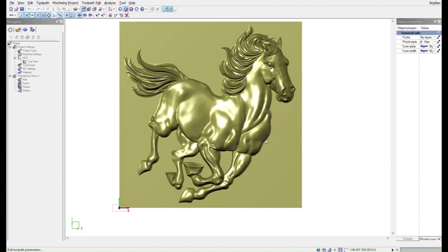So this basic tool's diameter is 12 millimeter, taper angle A means the entire angle of the taper, 15 degrees, and corner diameter is 4 millimeter, so I have given corner radius 2. And then you can create this tool according to your application. So and then okay,